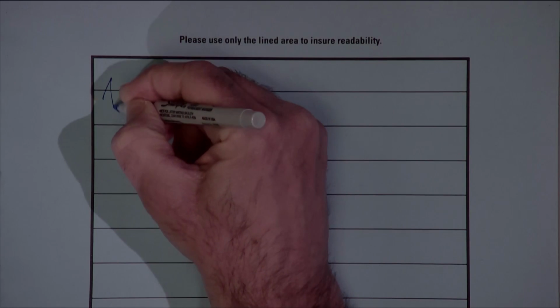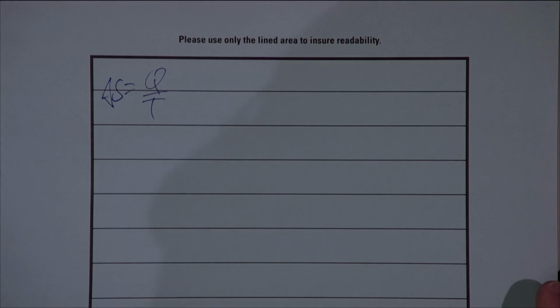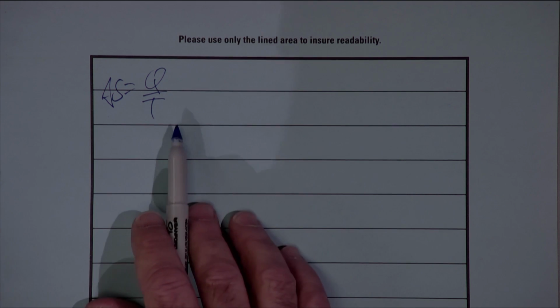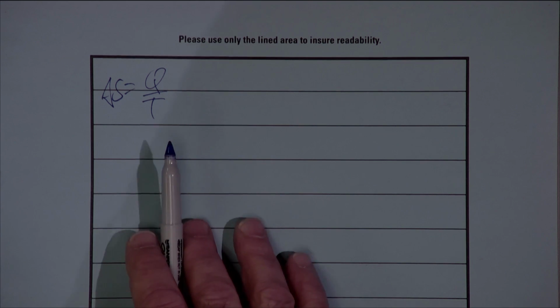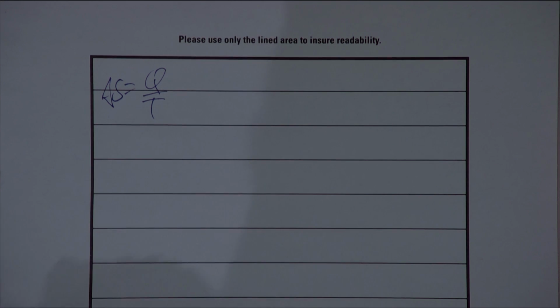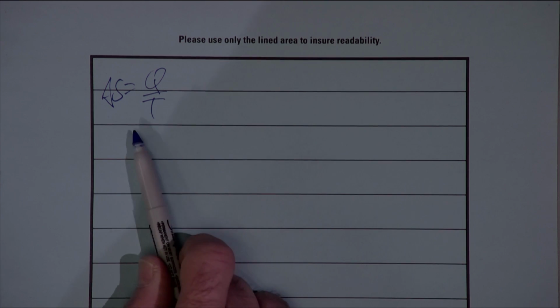All right, and then regarding the homework that was just returned to you, I think the biggest problem that I saw were students that were just using Q over T in order to find an entropy change. Now, you can only do that if it's an isothermal process, right? If it's isothermal, then we know that the integral of delta Q over T for the whole cycle is Q over T. In fact, I should say that it's for the isothermal reversible process. That's really the only time you can use this particular equation. Now, there were 2 or 3 problems in this homework set where you did have a problem that was both reversible and isothermal, so this is perfectly accurate.